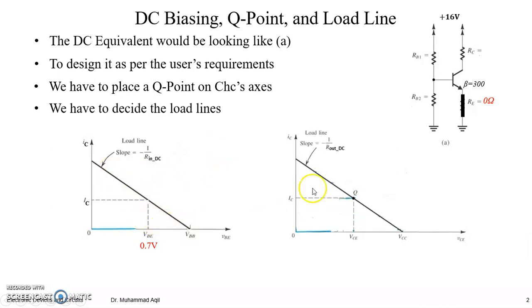If we find the load lines, we will be able to get the slope of that load line, and in our last analysis we knew that the slope is nothing but the resistance within that loop. So the input characteristics curve will give us the resistance of the input loop, and the slope of this output load line will give us the resistance of the output loop.